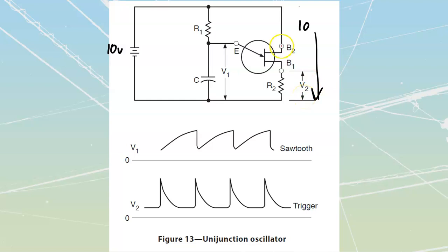Same deal as before. There is always going to be current flow through here that we are going to see. And that's fine because it's a high amount of resistance. So I'm going to start by just establishing one path of current flow that is never going to change. And that's going to be this path over here from negative through this resistance, through the silicon channel, and back over to my supply. There will always be current flowing through there.